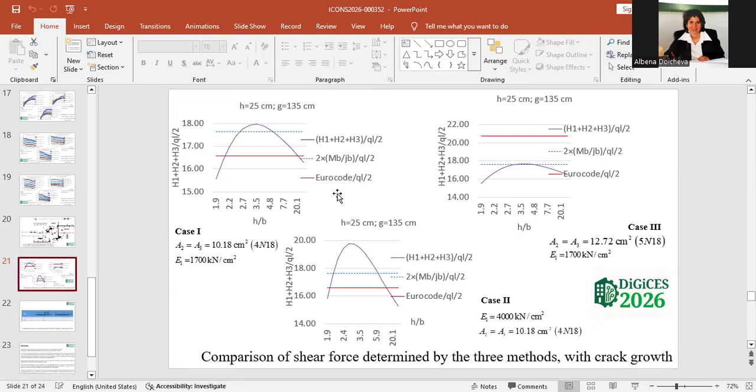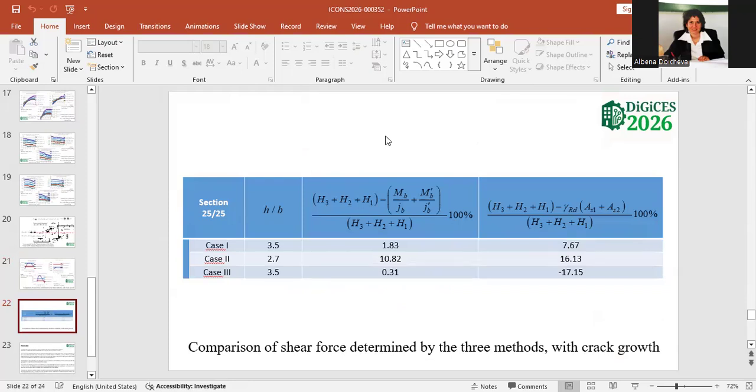When we use normal concrete and change the reinforcement bar, we can see that shear force is smaller than when we use more reinforcement bar, but the difference is not so big. The comparison between our shear force and shear force in the literature says that case 2 with high strength concrete gives us a bigger difference, and our shear force is bigger than that of literature.